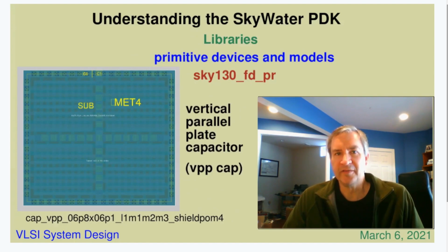Other specific device layouts in the primitive library can include bipolar transistors, varactors, high voltage drain extended devices, ESD devices, and an astonishingly large and confusing array of parallel plate capacitors of all shapes, sizes, and metal layers. I would tend to advise against using the parallel plate capacitor simply because there are MIM caps available which have a much higher capacitance per unit area without taking up all the routing area above a design.